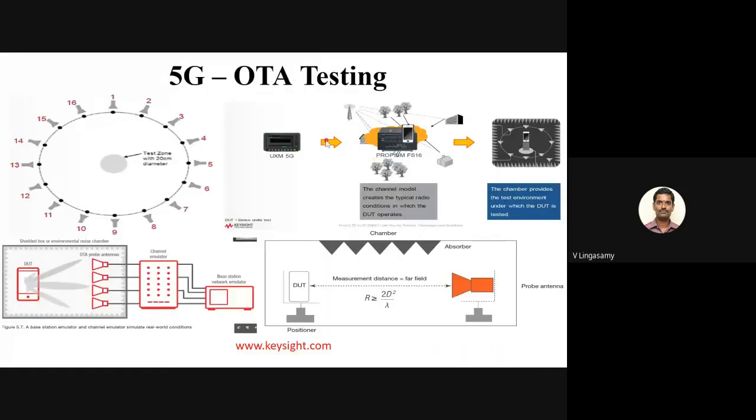And in 5G perspective, you cannot do just like that, right? You have to do a system level simulation, where in 5G, from Keysight there is a UXM. This is basically a node B emulator, or you can say base station emulator. Okay. Similarly, R&S has CMW500 and SMW500, like that. Rohde & Schwarz has many similar equipments, node B emulators and other stuff. Similarly, Viavi Solutions also has node B emulators and other stuff, and Tektronix, and many companies are working in test solutions basically. Okay, NI, National Instruments, many companies are working on that.